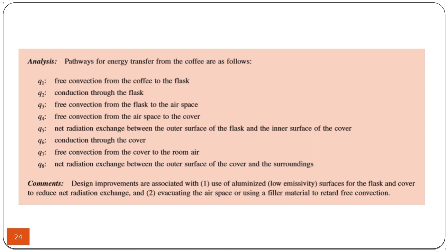So these are all thermal resistances. If you consider the complete network of the thermal resistances, this is why we have a very low heat loss from inside to outside, and this keeps the coffee inside the thermos hot.